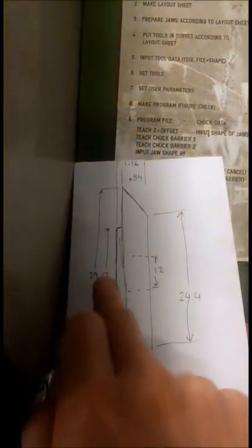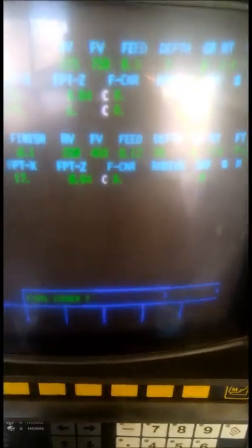Finish point in X will be 17, because we're just cutting down to there. Finish point in Z. Now this is still measuring off this side of the groove, so we still call this 0.84. Finish corner, we don't need anything in there because I want it to be a nice square end. Surface finish, we'll give that 8 again.